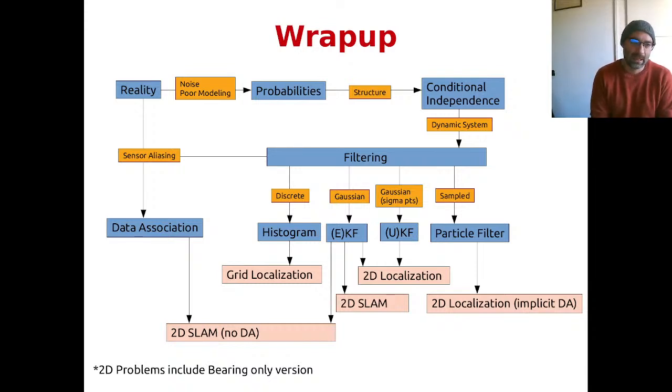Instead, with the mechanics of data association that we have provided you, one performs a suboptimal choice, but just picks at every point in time the best possible association, and then forgets the remaining part of the association tree. This is a choice that you're forced to make in case you're using a Gaussian filter, because a Gaussian distribution doesn't allow you to represent multiple modes. However, if we relax the assumption that our distribution is Gaussian and we are willing to pay a little bit more computation and memory to represent a distribution in sample form,